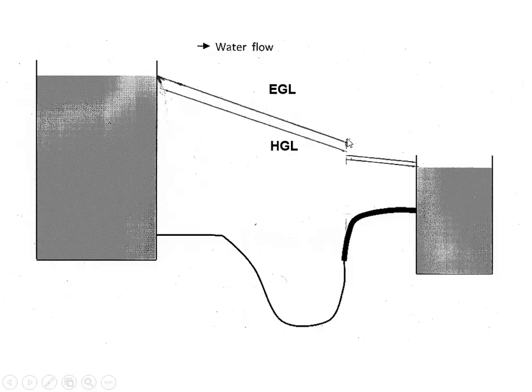Now, I showed that there's a sudden drop, and that's because of the expansion here. That pipe expansion, I'm saying that there's a sudden local loss accounting for the decrease in pressure there. And then the EGL and HGL are supposed to be parallel. My drawing skills aren't 100%. It may be that it visually looks like it's a little bit further apart here than there, but that's accidental, not by definition.